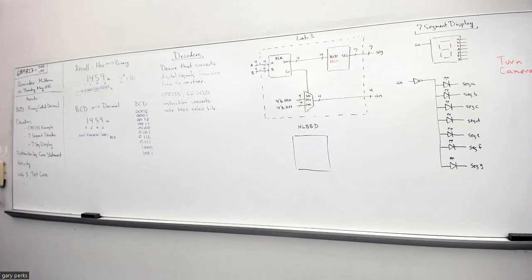And if you look up where there's a /7, for 7 bits, it goes up to IR6 to 0, which is another 7 bits of an instruction. You'll learn in that class that the instructions for this microprocessor are 32 bits long, and the decoder is taking certain bits and converting them into outputs.